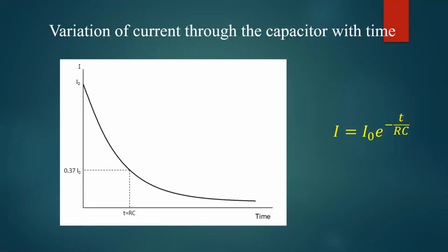So one point you have to remember, in case of series RC circuit, during charging of the capacitor, charge and voltage have the same nature of behavior, a similar equation, and both the charge and voltage increase and the current through the capacitor decreases. Note this particular point. During charging, both the charge and voltage increase. Charging means charge should increase, voltage should also increase. That is the meaning of charging. Whereas current decreases. That is a very important point.